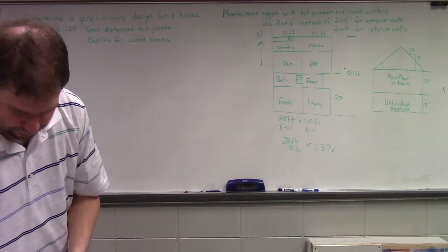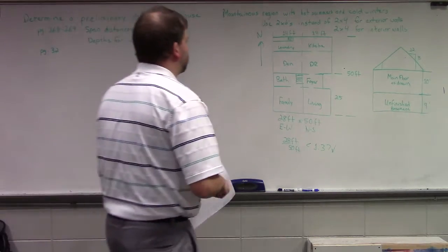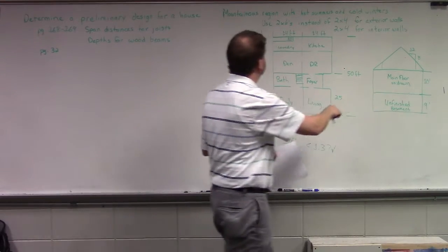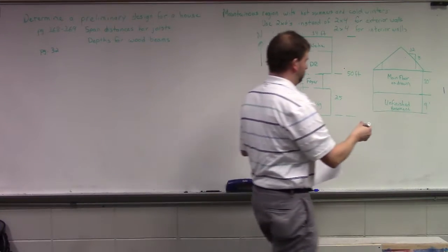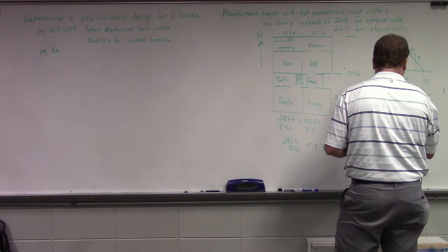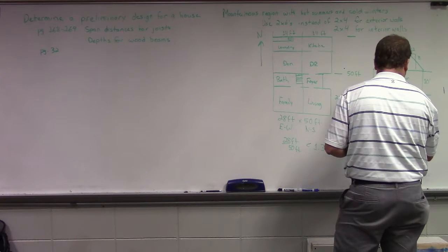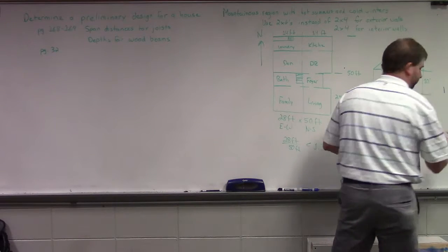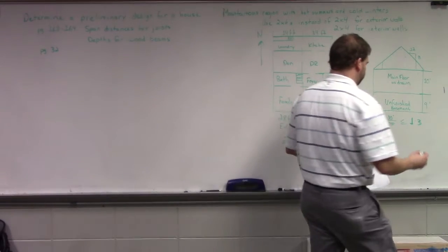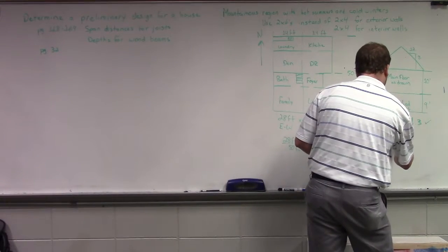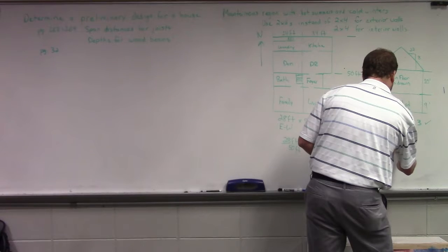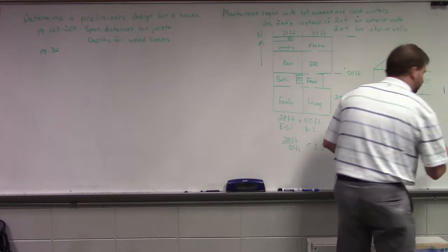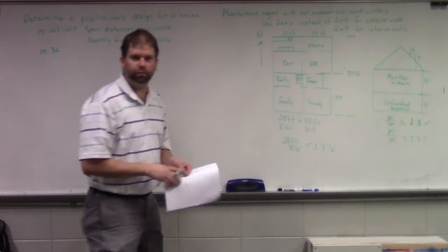Okay? We should also keep in mind, what about our shear wall? So on the main floor, we've got a 10-foot distance, right? So our 10-foot to our 28-foot isn't going to be an issue, right? It's 1 to 2.8, so that's good. The 50 foot, that one's rough, that was 1.5. That's gonna give us a problem, right?